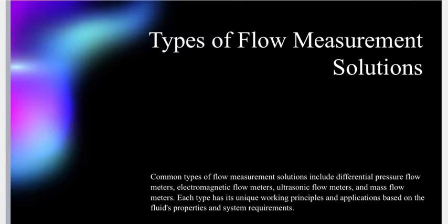When the fluid flows through the pipe, velocity increases and its pressure decreases. The pressure difference before and after is measured and used to calculate the flow rate. We studied all of these things in thermodynamics. It has features, advantages, disadvantages and also applications. Its features are that it is simple and widely used, low cost, and stable for liquids, gases and steam.